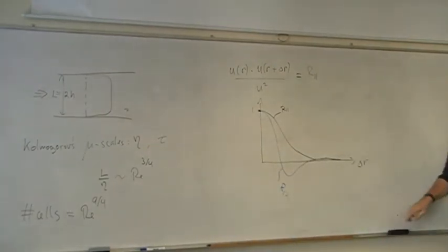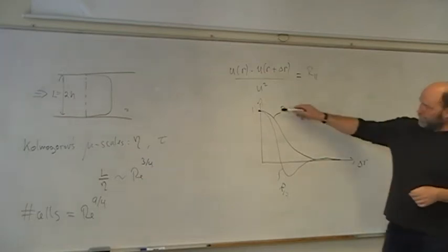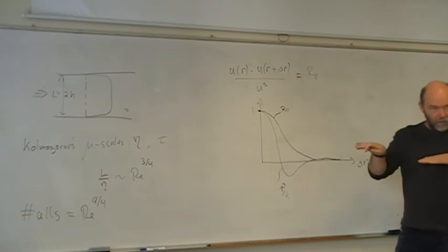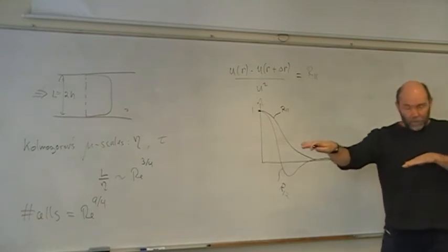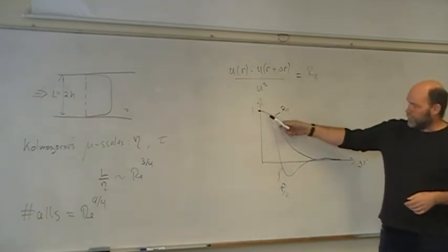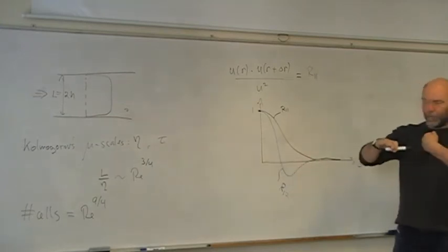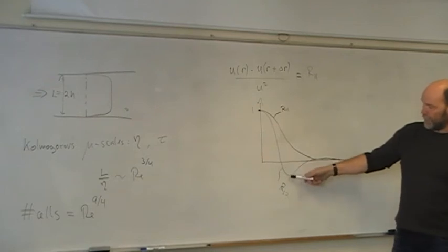So these coefficients, these functions, can tell us something about the flow. Here we have some long structures in the x direction. They are correlated, they talk to each other, while in the cross-stream direction they go negative, so they will be telling the opposite at a certain average distance.